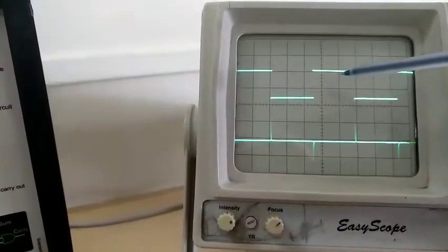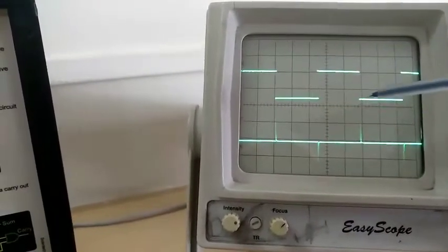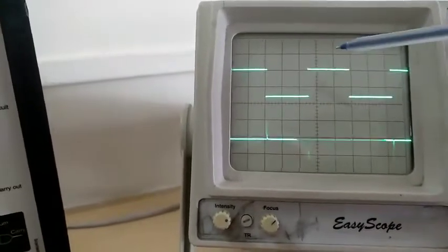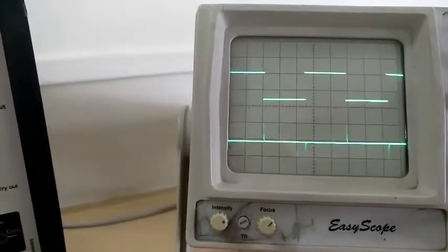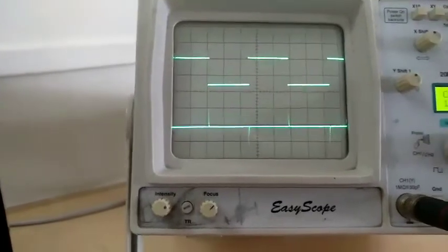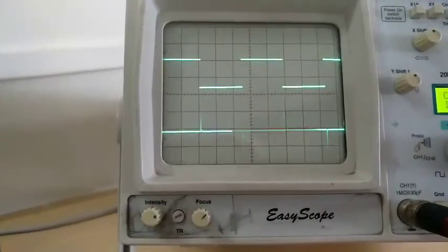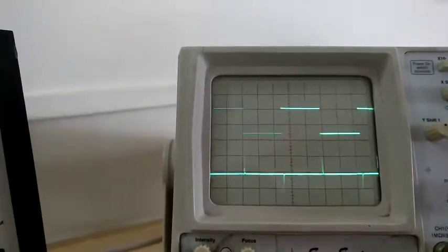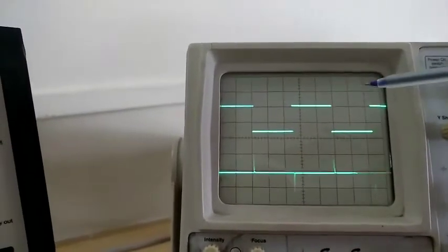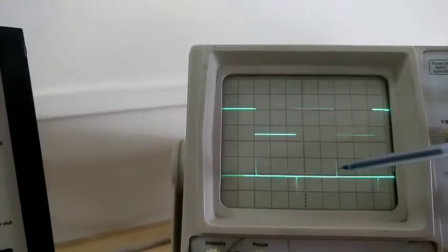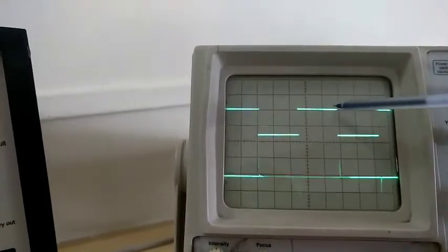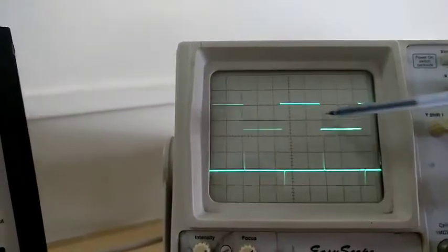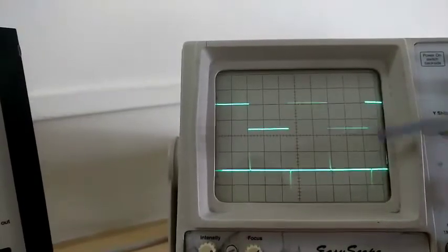So the differentiator will differentiate the input square wave, because we know that for a constant value we get a 0 output. As we are providing input to the inverting terminal, we will get an inverted output. For positive we get a negative spike, and for negative we get a positive spike.